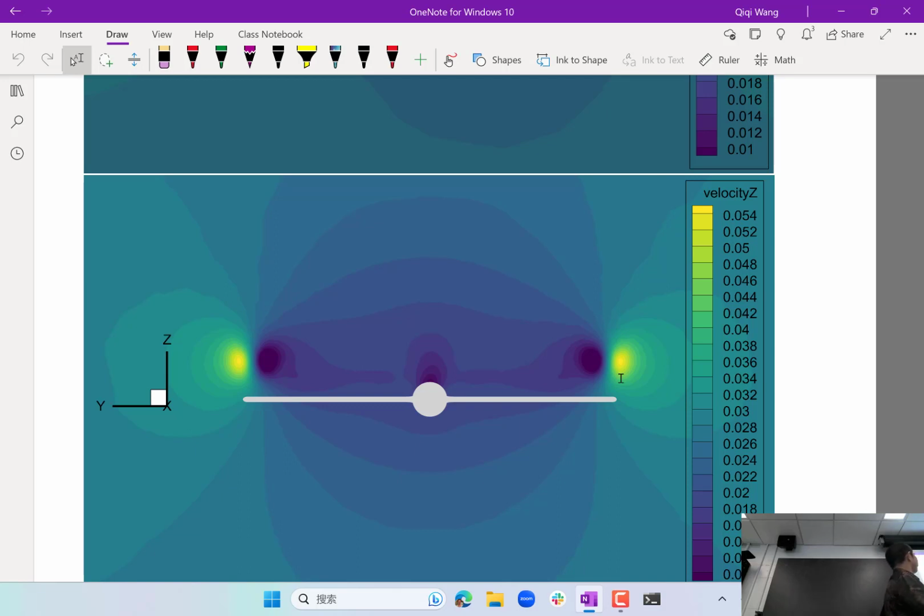We're going to look at computational fluid dynamics towards the second half of the course. But in CFD, it's much easier to keep the same mesh and change the free stream conditions when you want to change the angle of attack, rather than having to rotate the geometry and the mesh but use the same free stream condition, right? That's why usually the x-axis is aligned with the airplane model itself, rather than with the free stream. But if you're able to align with the free stream, you're going to see the center of the vortices would be not only inboard a little bit from the tip of the wing, but also a little bit lower. Okay, questions?